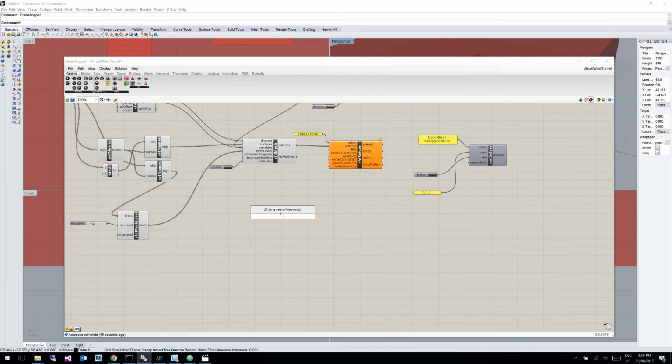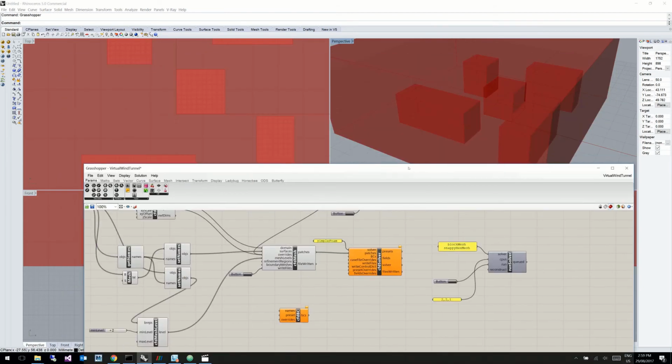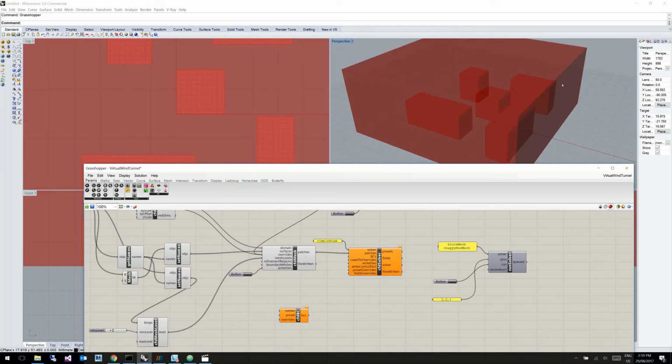So to add boundary conditions, we just add a CFD BC component, and by default all the objects are wall type objects, and the CFD domain has special names on the outer patches of minX, maxX, minY, maxY, minZ, maxZ, and so on.